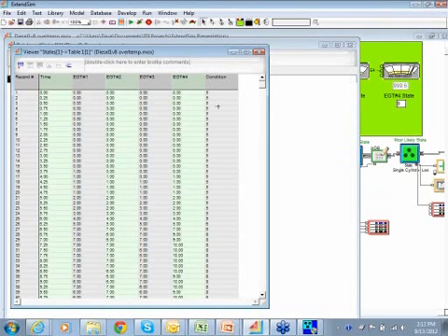You can see that condition 5 was the low state. And then as I went along, the interesting thing is that I get a transient here where it goes to state 9, which is an unknown state, just as the engine is transitioning between low and normal operating condition. And then it goes to 6, which is normal on all cylinders.